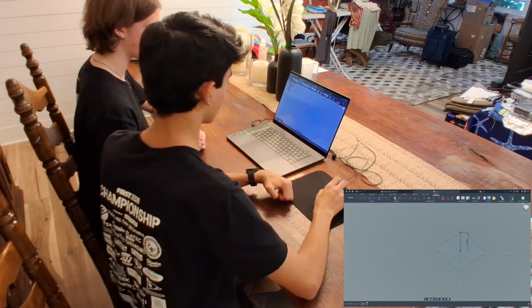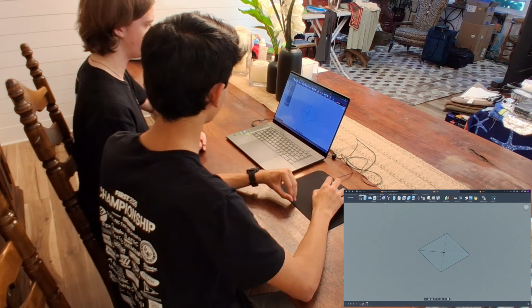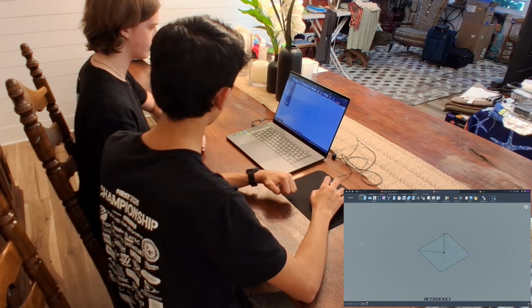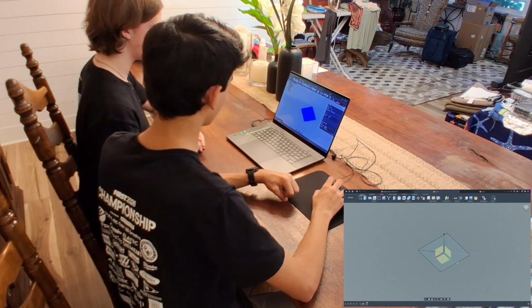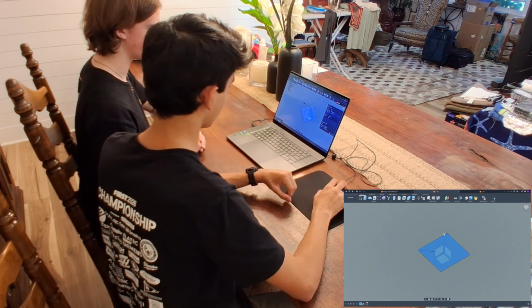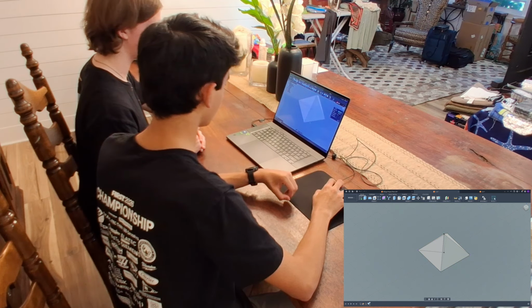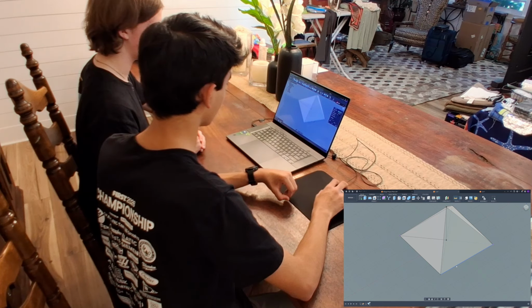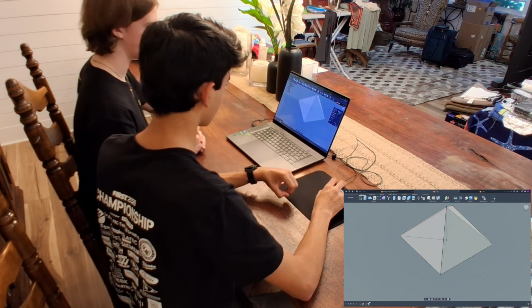Alright. So now we have this vertical line coming up with the right height. So what we're going to do is come over, finish our sketch. We're going to loft it up from that square face. So we're going to find our loft tool, bring it up to that point. And then now, just so we can check, see that's a side length of 1 inch. Come over here, and that should also be 1 inch, and yes it is.